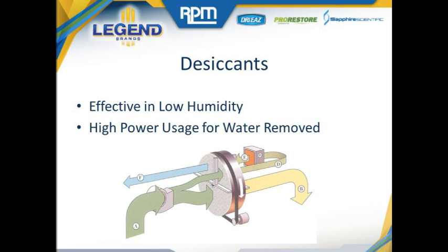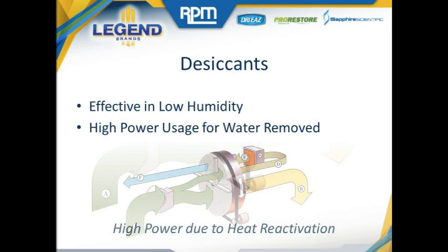This is because a heater must be used to reactivate the silica gel or lithium chloride that the desiccant is based upon. High power due to the heat reactivation means that significant increases or losses in energy efficiency are important to consider when looking at desiccant dehumidification.